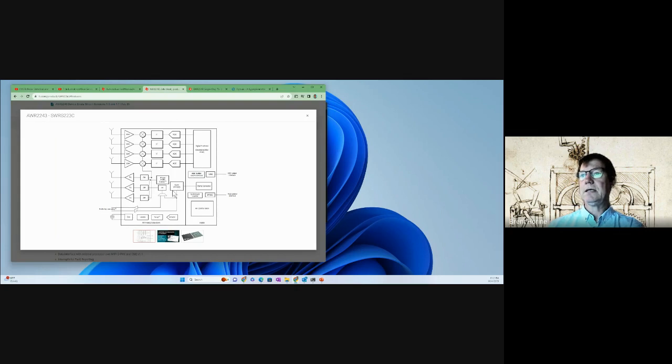The key here is a synthesizer and this ramp generator being able to create that linear chirp. You're going to create, in this case, a 20 gigahertz synthesizer, and you're going to ramp that over time, and then you're going to do a frequency multiplication by 4. So you're going to get up around 80 gigs. And then that's going to go to some phase shifters to tweak the transmit signals, and then amplify them and transmit them.